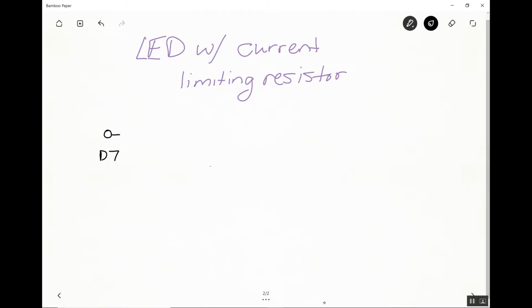And then a wire from digital pin 7 on the Arduino is going to go to your breadboard and connect with a resistor, which is about 200 ohms in size. And then the resistor will be connected to a light emitting diode, which then is connected to 0 volts or ground via another wire on your Arduino.